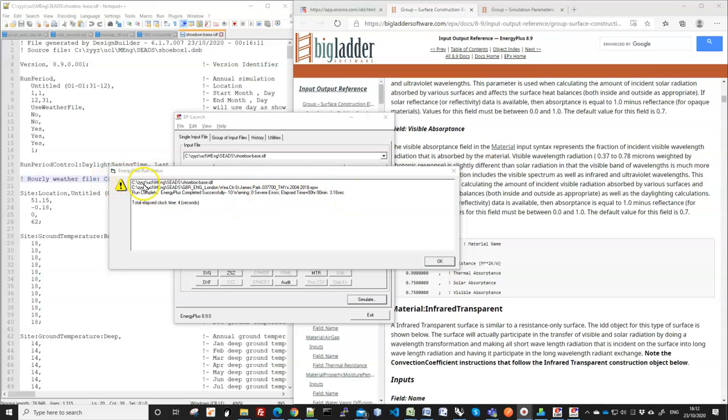Okay, here it shows the EnergyPlus run status. You can see the run has completed, and EnergyPlus completed successfully with 10 warnings. Now, if you see some warnings, normally they're not a big problem, but you should check nevertheless. But if you do see some severe errors, then you should definitely pay attention. Now we can close that.